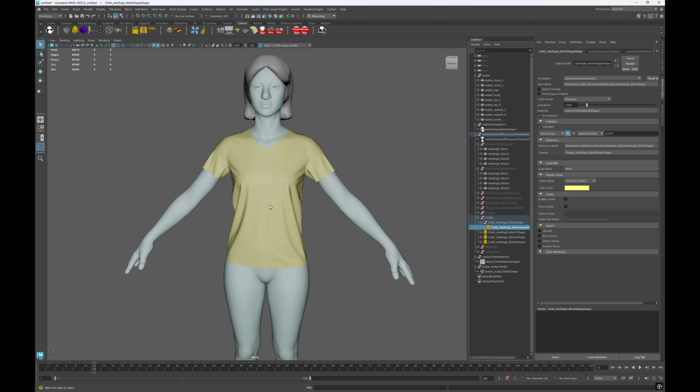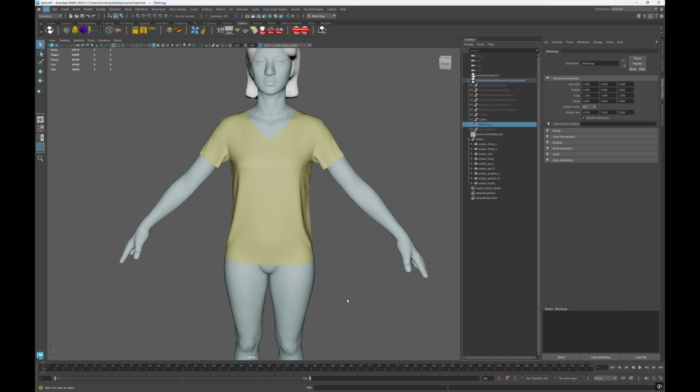So this was an example from CLO where we used the fitting simulation and a material property. If we had simply exported the default fabrics and default simulation settings, we would have got rather a different result. And as you may actually be given that output, let me show you how to deal with that. So this scene has a start mesh from CLO where we used the standard default fabric and the standard default simulation.